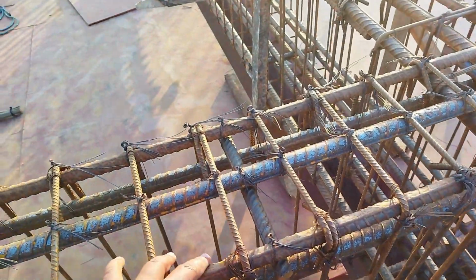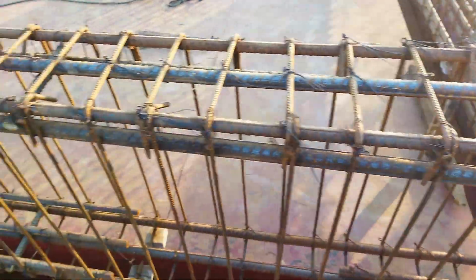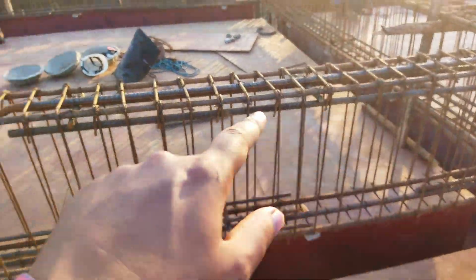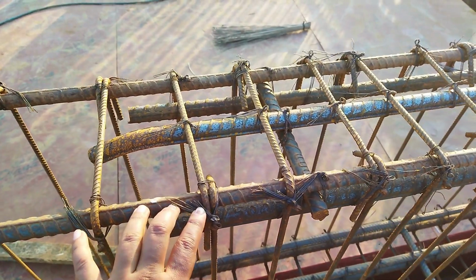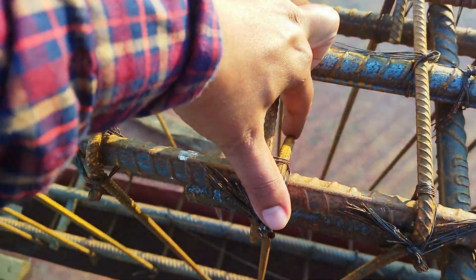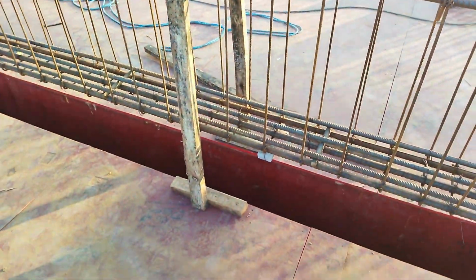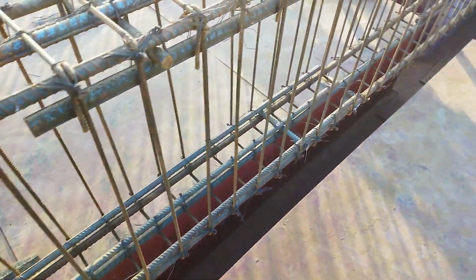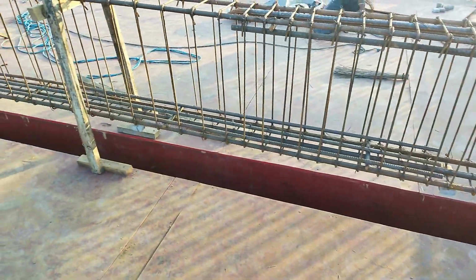As you can see here, we have 4 bars of 20 mm at the top, and in the bottom also you can see the extra bars. You can see how the spacer bar is also given. You can see a spacer bar of 25 mm is also given to separate between the two. You can also see the bottom reinforcement, extra bottom. The extra bottom will start from here, that is at the center. You can see the extra bottom reinforcement.